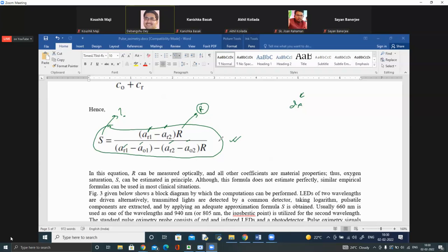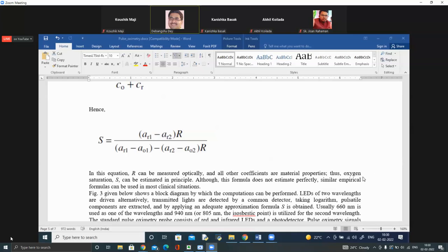So that is why there are different types of instruments, low cost, high cost. If your instrument takes care of so many factors, then all those calculations and measurements are incorporated, and that is why the cost will become high. So there are different instruments, and they require frequent calibration and maintenance. Because if your photo detector is kept at your home, and some dust and other things are deposited on the photo detector, the intensity will automatically be low, so you will not get the true reading.